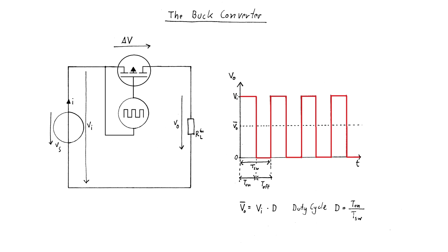But there are some loads which can. For example, the good old light bulb. The light bulb will only be destroyed when over a certain period of time a current passes through it which exceeds its ratings, causing the filament to overheat and burn through. But when fed with extremely short pulses, like in this case, the light bulb is just fine with the mean value of its rated voltage. The light bulb will also flicker in the frequency of the PWM. But the human sense of vision is much too slow to even notice that high-frequency flickering.